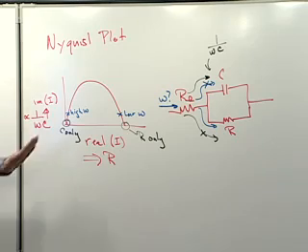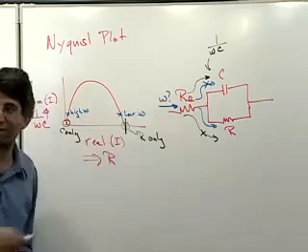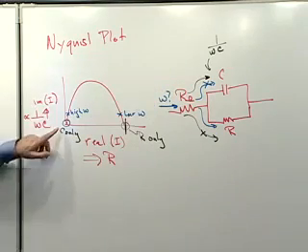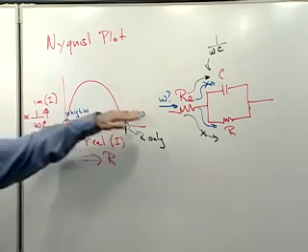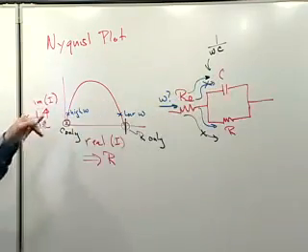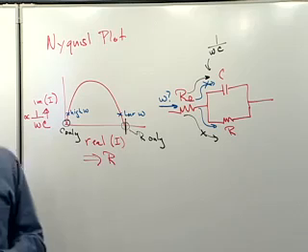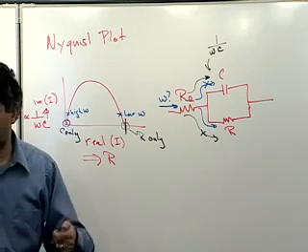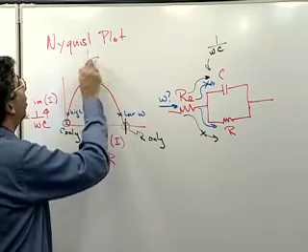Right? All the currents here. So when I measure this point, I'm measuring the resistance of this circuit. And when I'm measuring this point over here, there is no resistance from the resistor because everything's going through this upper branch. And I'm looking at the capacitance of the system. And you can show that when you're right in the middle of the semicircle here, that's 1 over the RC